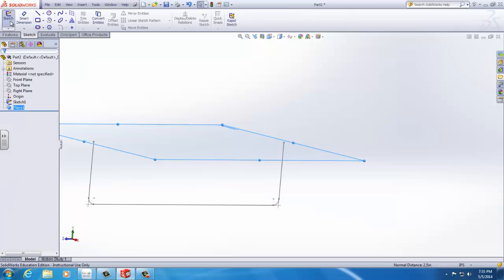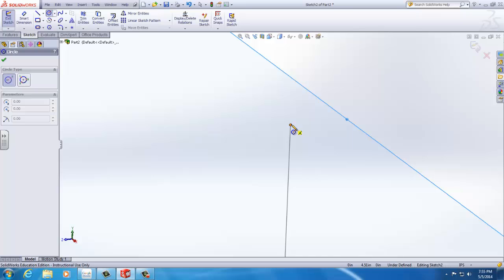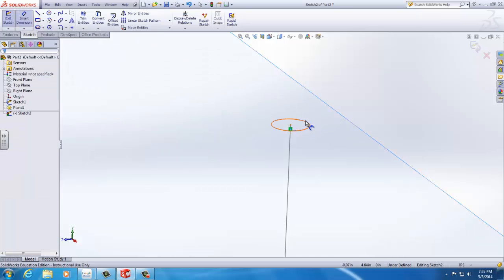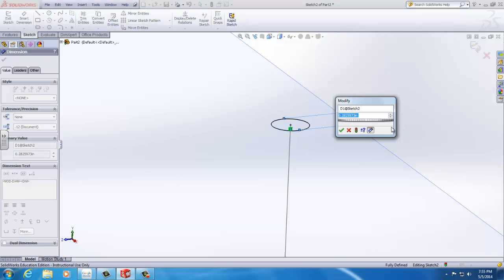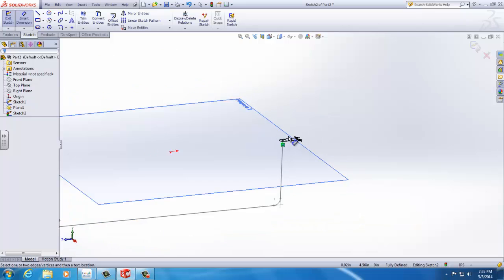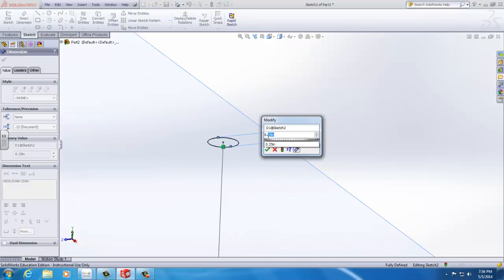We start our sketch on that plane. So we have that. Hope you guys can see that. And we create that circle at that same point we're looking for. If we can't, I unselect that; if you like, you can adjust it based on the points. At that point, I should have added a center point and a quick dimension. It would have helped me adjust it better. If I don't have that, it's alright. That's going to be the thickness of the wire. Go thinner. And then you select the point where you want to insert it. And from there, do 0.125, half, and you can adjust it.